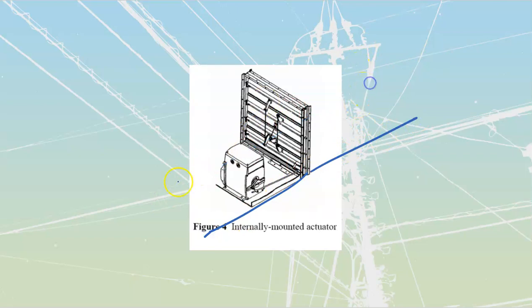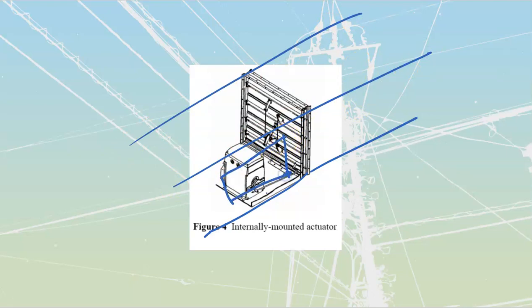So if I take a look at this one here, it's going to have my duct like that going around it. Anytime that you see those doors on the side of ducts, they're going to be a riveted-in type of door that's openable and closable. It's usually because we've got dampers inside of there, or a coil, or something else that needs servicing next to it. We need to be able to access all electrical boxes and controls, including our junctions onto motors. So if there's a motor, there has to be an access plate for that thing as well.